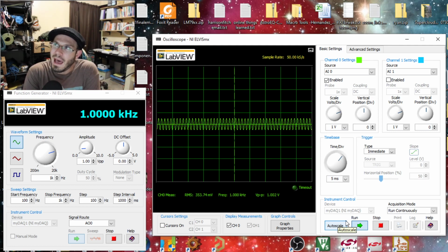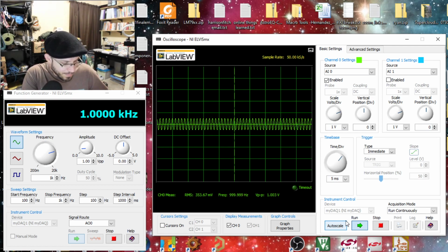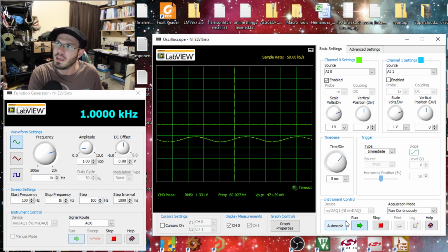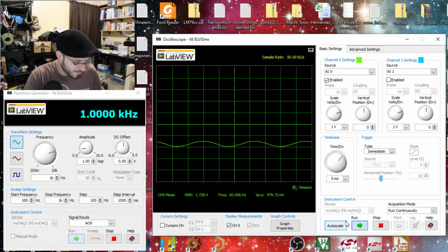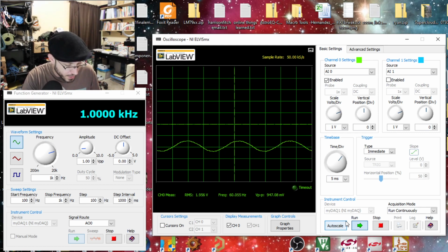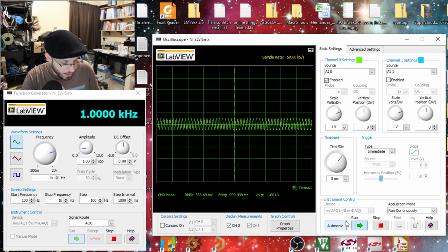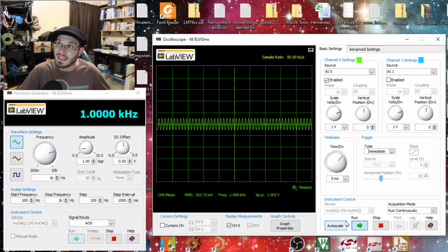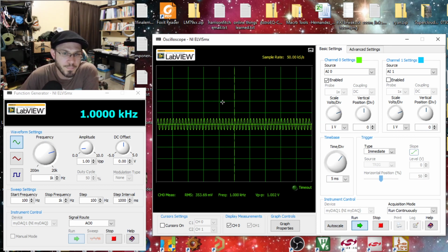And if I go back to my board, I'm going to disconnect the function generator, that white wire. I'm going to unplug it. Oh, sure enough, we lost our signal. We're still picking up something, but that's coming over on the ground, and that's actually just noise, because both wires from our analog input need to be connected in order to see anything. So again, I'll plug that back together. So it looks again like we are reading the output from that function generator.